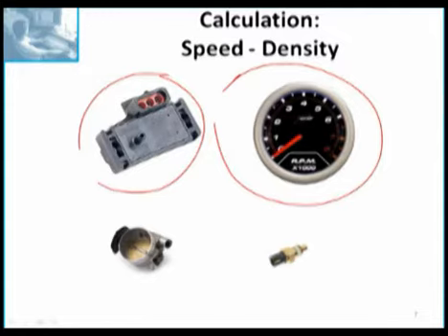So the best place to test a MAP sensor is key on, engine off. And it needs to be comparable to the baro that you have seen on good running cars at your location. The weather station baro is not how you want to compare a MAP, because the weather station baro is corrected for elevation. And so at my house at 3,000 feet, a car would show me a baro of 27 inches, but the weather station on a sunny day would say I had 30 inches of barometric pressure. It's a different thing. So you want to look at some good cars, see what the baro reading is, and that becomes your number.